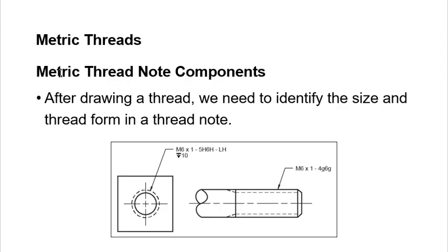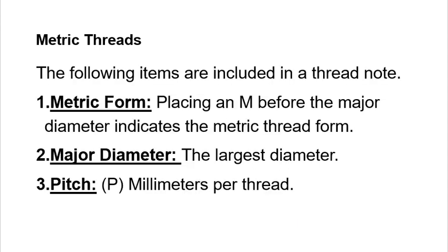Then we'll come into the metric system. Let's see how we do the thread note. The same thing, you draw it, and then you identify the size and threads in your thread note. A big picture, it looks like this, and then we'll get into the details of it.